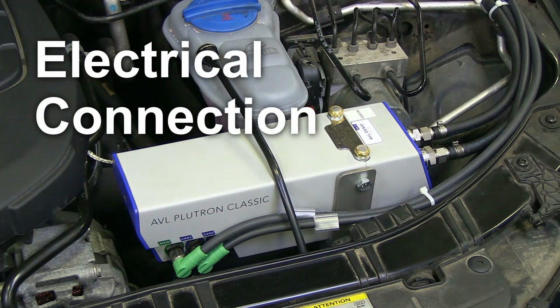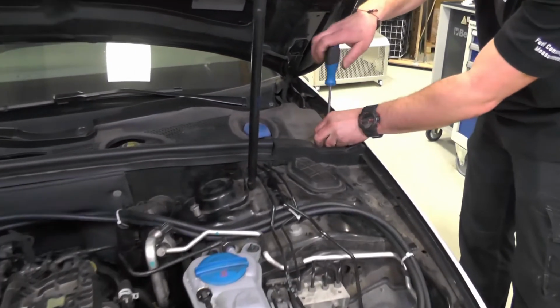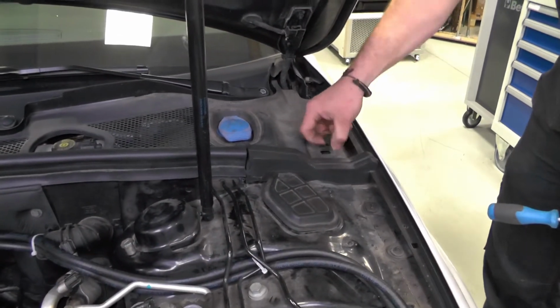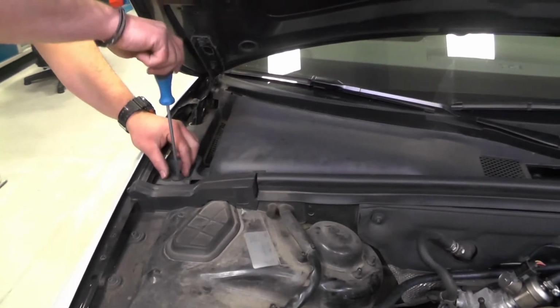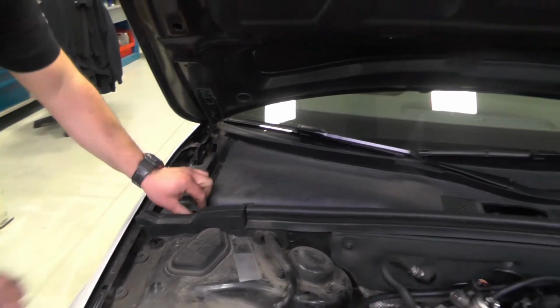Now we are ready for the last step, the installation of the electrical connections. First we need to remove the top cover to access the battery terminal connector box in the engine compartment for the power connection.